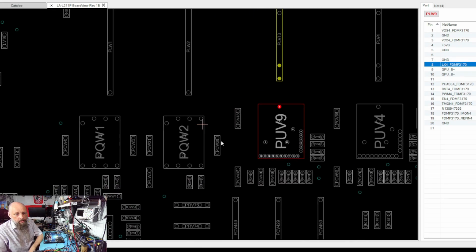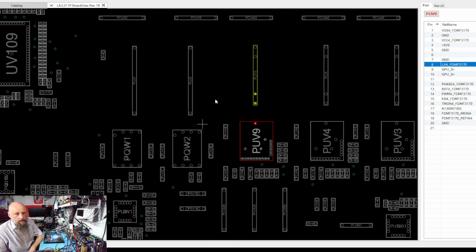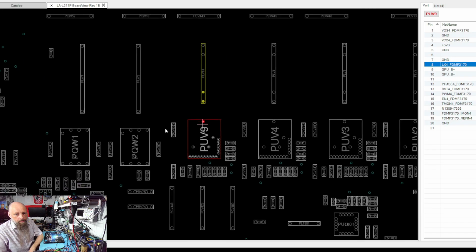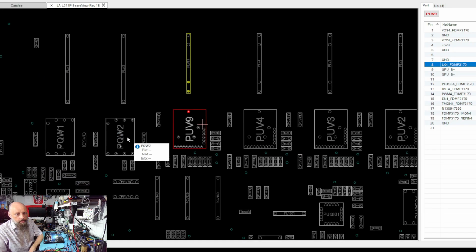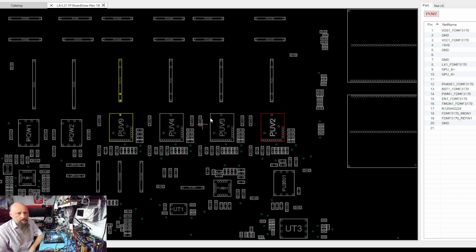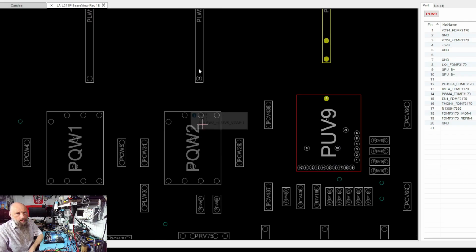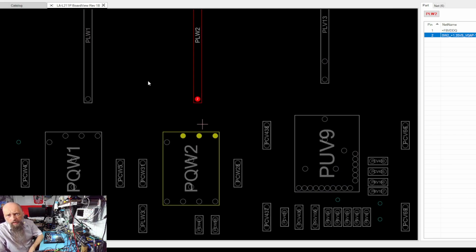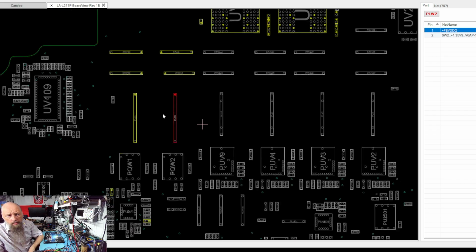This is the pin they take voltage from, right? Why is this one different? Okay, so all 4 resistors just supply these 4 chips over here, right? So this one is not vCore. This is feedback, it says.